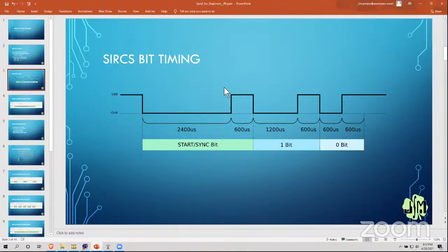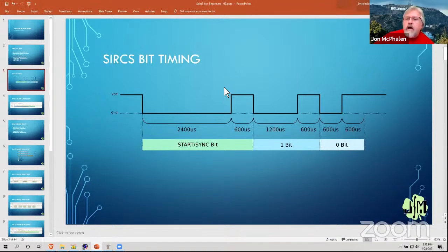Are you going to just send a stream of data out to the Processing app? Yes. So every channel will have a value, and there would be a status value too, because what happens with S-Bus, we're kind of getting ahead of our initial presentation, but the S-Bus receiver will say, hey, I think I lost the signal, but here's the last bit of data I had. When it figures out that the signal is really gone, you get another status thing. So you can actually see that.